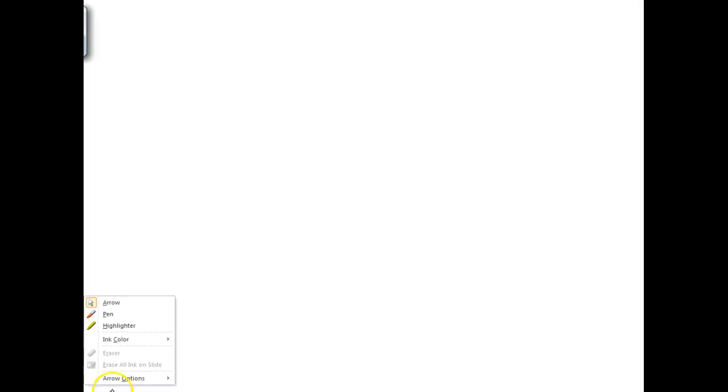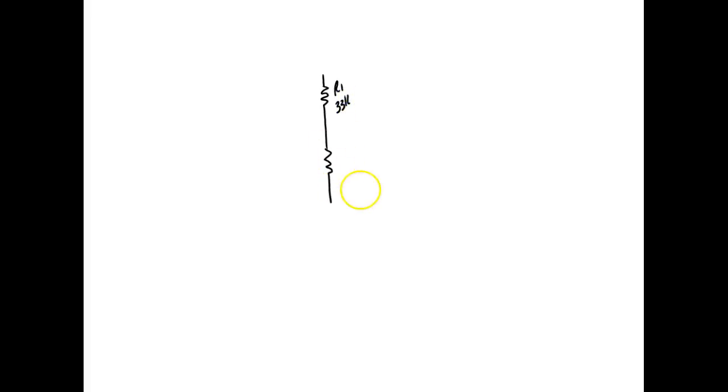So our circuit, in my opinion, is a lot easier to calculate. It's a voltage divider bias. Here they're calling R1, and it's a 33K. Here they're calling R2. This is a 39K. By the way, you notice that this has been changed. I actually changed it. The way they had it biased in the book was awful.